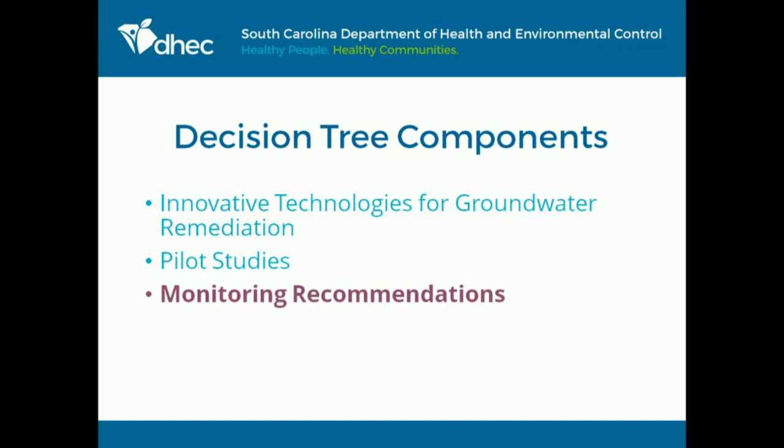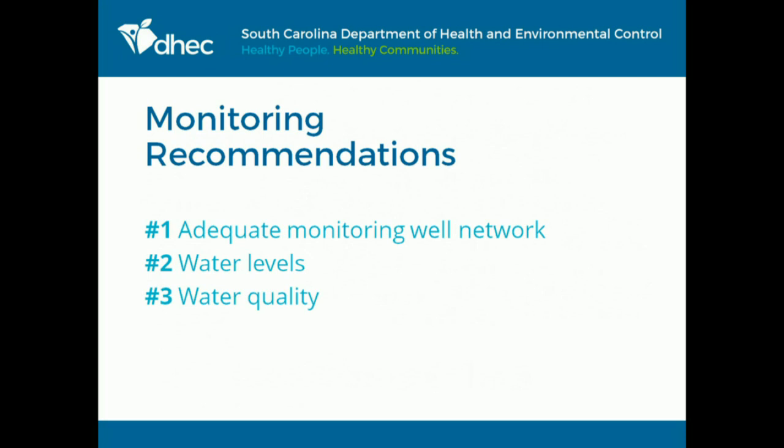So monitoring recommendations. I've got several of them. First of all, adequate monitoring well network. If you do a pilot study and you have 3 monitoring points, I'm sorry, but that's a waste of your time and their money. Water levels, especially if you're doing injection technologies, but even with other ones, water levels are going to tell you something. And thirdly, water quality.